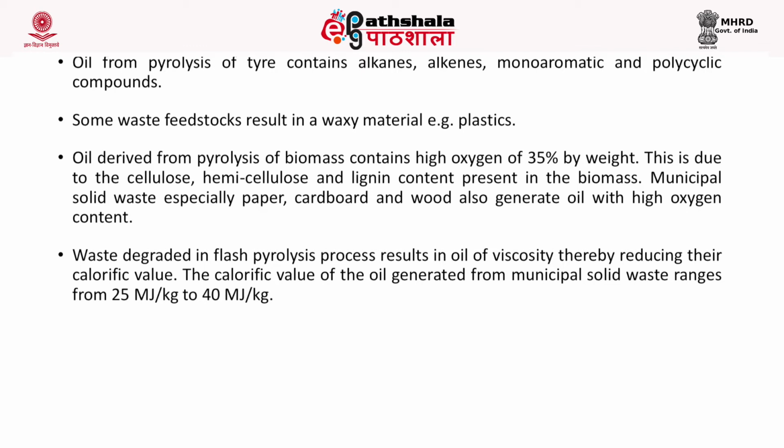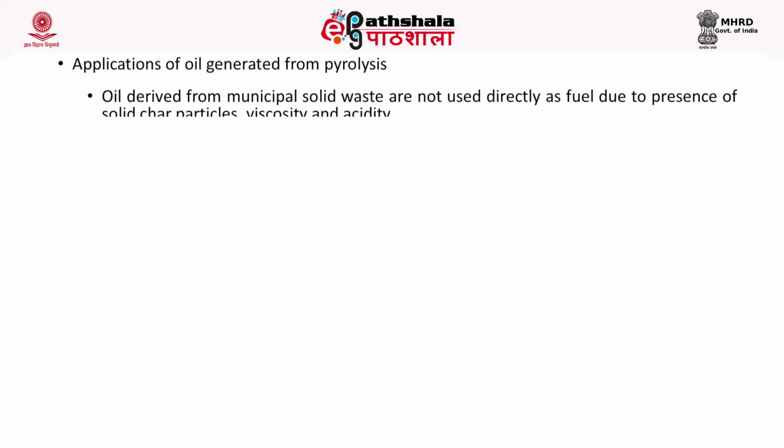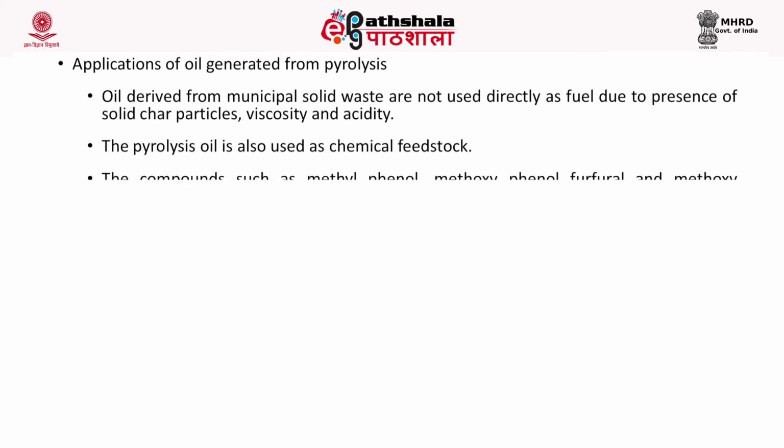Waste degraded in flash pyrolysis might result in an oil of high viscosity, thereby reducing its calorific value. The calorific value of oil generated from municipal solid waste ranges from 25 megajoules per kg to 40 megajoules per kg. The oil generated from the pyrolysis process has a wide range of applications.